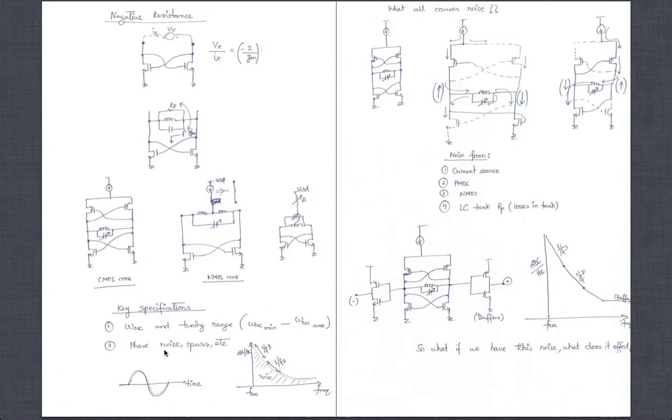And why is this important? Let's step back and see, what is this VCO trying to do? It's trying to generate a frequency. Let's say I wanted a 2 gigahertz frequency from a VCO. You want it to be 2 gigahertz. You want it to be very, very clean, by which I mean there shouldn't be any noise. This is hard to see maybe, but I can still explain it. This is a sine wave, the solid line, and let's say it's a 2 gigahertz clean sine wave. But once these elements which are there start adding some noise, there will always be some noise added to this system.